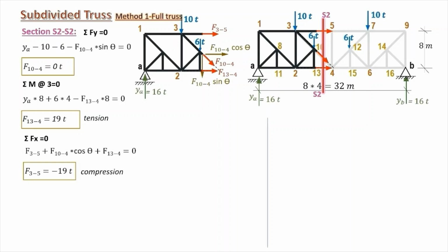So if we have two components, say in the y direction, it is a wise procedure to start with the perpendicular direction, x direction, if it carries one equation and one unknown, and vice versa. Or we choose a point, a joint, around which we take moments to cross out the unknowns and keep us left with one unknown in the equation.